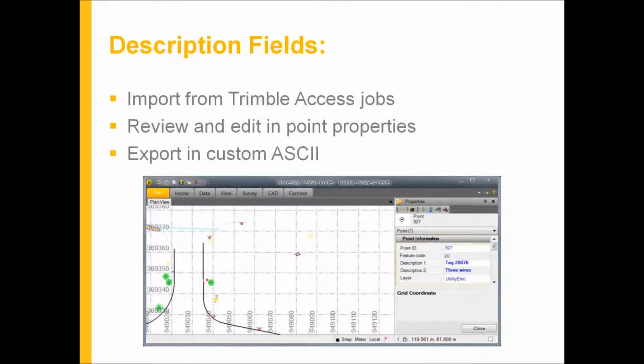By doing that, when you run out your line work on the controller and use your feature codes and also process them in Trimble Business Center, it's using the exact same symbols, line styles, codes and colors and layers that you're using in CAD. So it makes the transition from the field to AutoCAD a little bit easier. Essentially you can bring it into TBC, process your codes, get all your symbols and line work, export out a DWG, and it comes right into CAD, and everything's the same across the board. It makes life a lot easier.